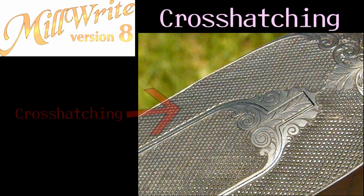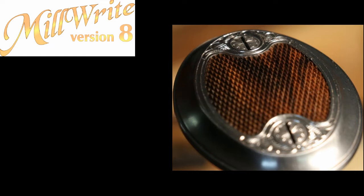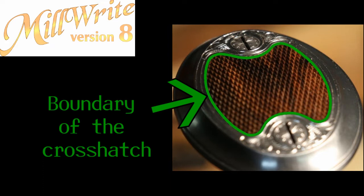MillWrite now has two different ways for doing crosshatching, and it can project the crosshatching onto a 3D surface. I'll show you how to crosshatch this particular shape. To begin with, we need a polyline of the boundary to show MillWrite where the crosshatching should be.